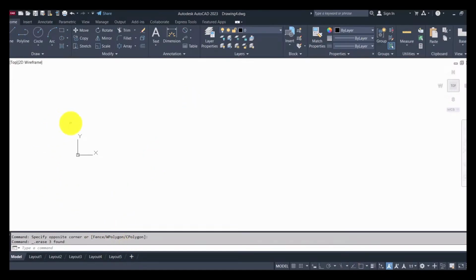So the last drawing tool we'll be learning here is rectangle. We are taking a look at some of our drawing tools, not all of them, then a few modifying tools too, in order to help us achieve our exercise for today. A rectangle has 4 corners. In AutoCAD, to draw a rectangle, you need 2 diagonal corners.